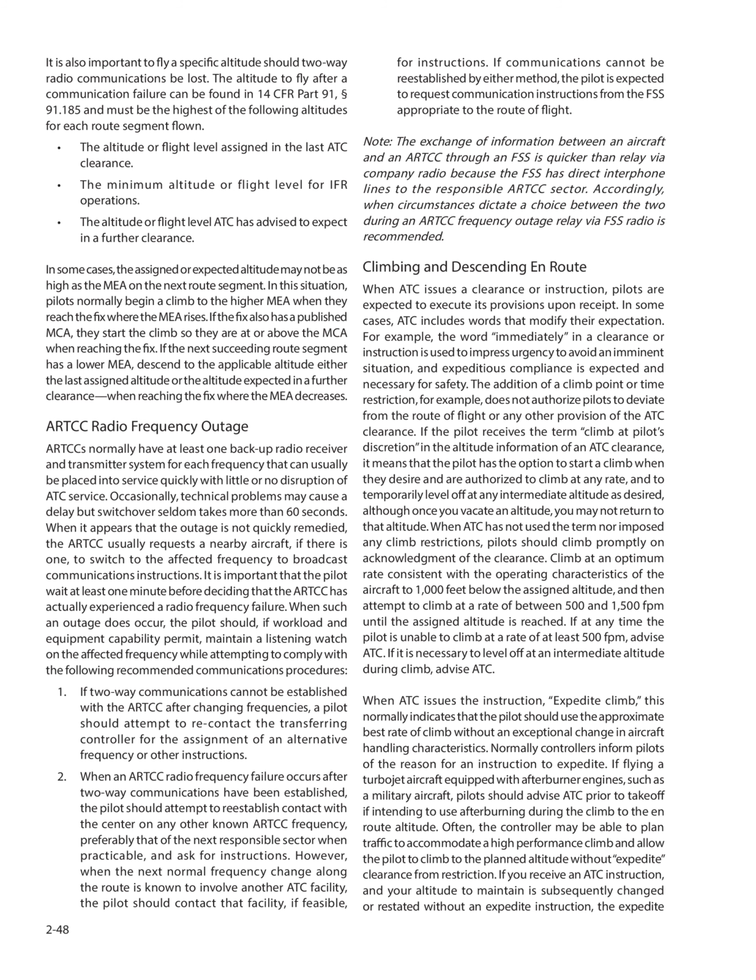It is important that the pilot wait at least 1 minute before deciding that the ARC has actually experienced a radio frequency failure. When such an outage does occur, the pilot should, if workload and equipment capability permit, maintain a listening watch on the affected frequency while attempting to comply with the following recommended communications procedures. 1. If two-way communications cannot be established with the ARC after changing frequencies, a pilot should attempt to recontact the transferring controller for the assignment of an alternative frequency or other instructions.